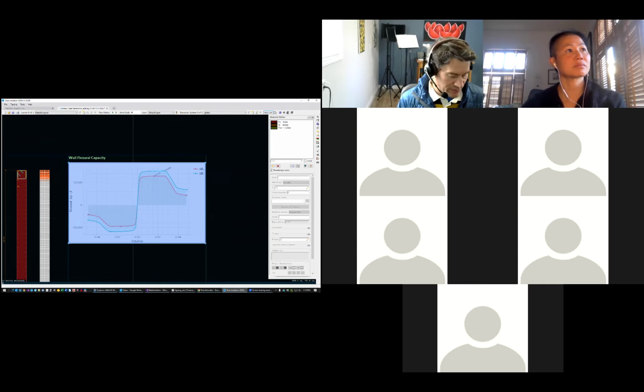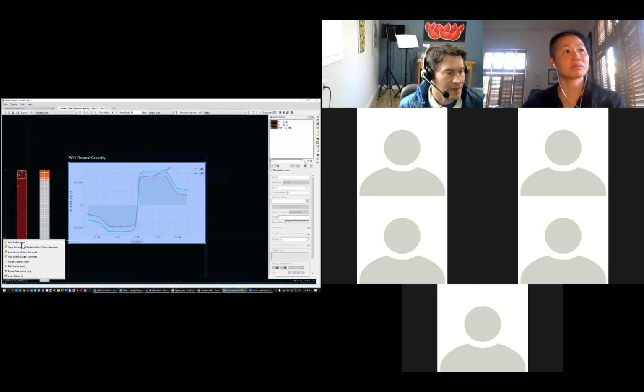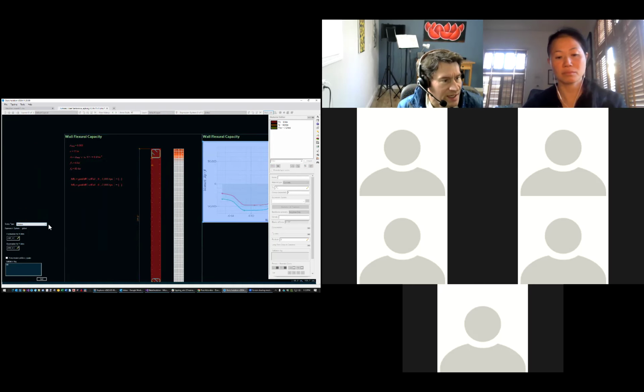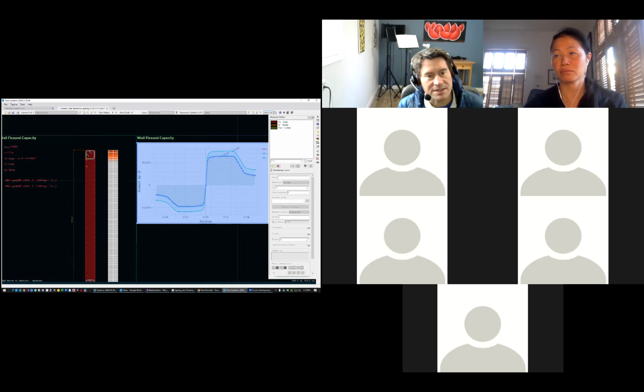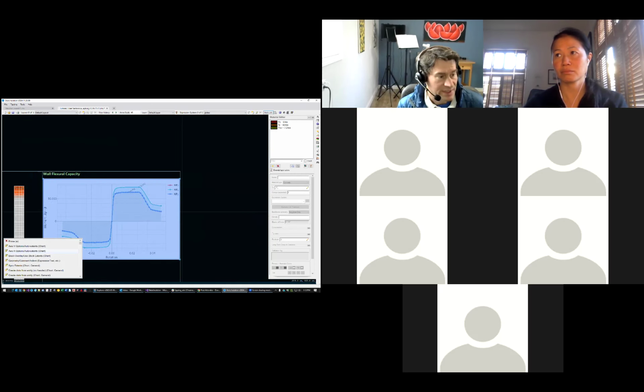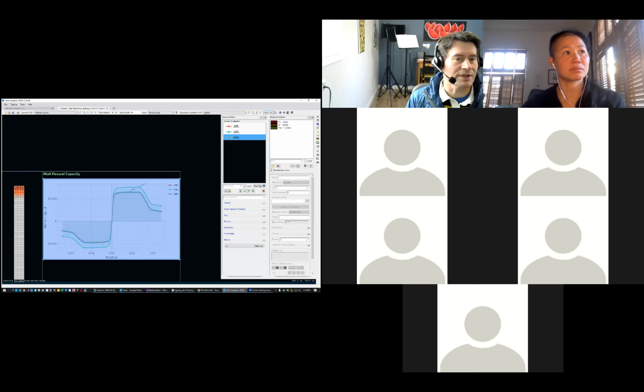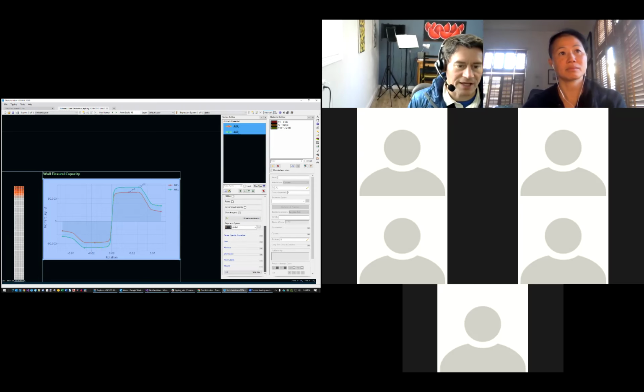I have these series on here, but to add a series, we push SER, add series, and we can go to vectors, which is just plotting arrays of data, and we say X expression includes X, Y pairs, and then we type in a reference to the symbol MR1, which is right there, and we click add, and now I just re-added that series. We type EDS, edit series, to bring up the edit series sidebar, and I delete the one that I didn't want.